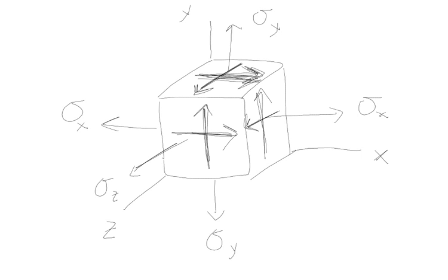Now, why 2 shears on each face? Well, keep in mind that we want our stresses to coincide with our coordinate directions. So on each face, how many coordinate directions do I have in the plane of that face? Like on this top face, I want a stress that's in the x direction and one in the z direction. I can't have one in the y direction because that's my normal direction. I already have my sigma y there. Likewise, on this face on the right, what I want is a shear stress that coincides with my y direction, and a shear stress that coincides with my z direction. There's none in the x direction because that would be my sigma x.